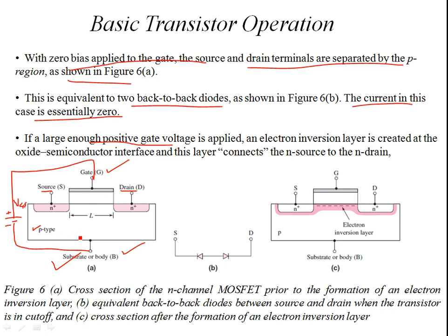to have charges on the plate and on the substrate. Due to this, I'll have the accumulation of positive holes on the bottom of the substrate. Okay, and owing to the minority negatively charged carriers, I'm going to have some depletion negative space charge region, which is not going to consist of majority carriers of the p-type, which are the holes. So due to this establishment of this channel, you are going to have a current.